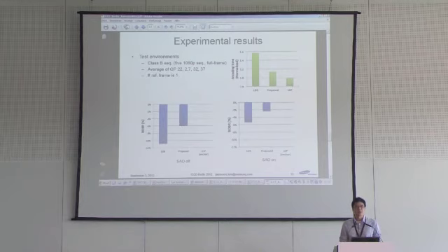The SAO, sample adaptive offset, is a kind of post filter. If we turn off the SAO in the encoding, the coding gain gap between low delay B coding and low delay P coding is about 10%, which is very large. But with the proposed method, the coding gain is up to 6% over LDP coding, and the encoding time is about 70% of the low delay P coding.